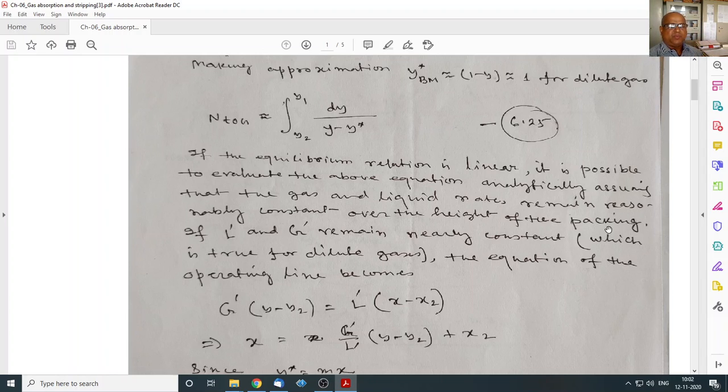So let's take you put 100 mole of gas at the bottom, then if total absorption happens, 99 mole of gas will go to the top. So only one mole will transfer from the gas phase to the liquid. So 100 to 99, you can consider this as constant. Similarly for the liquid, if you take 50 mole, now it would come out as 51 mole.